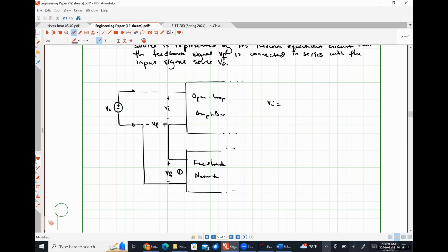If we had positive feedback, it would constantly cause the input signal applied to the amplifier to get larger and larger, eventually driving our output to saturation, which is what we are trying to avoid with negative feedback. So that error signal is nothing more than VS minus VF. A small portion of the output is subtracted from the input signal in order to keep our output stable.